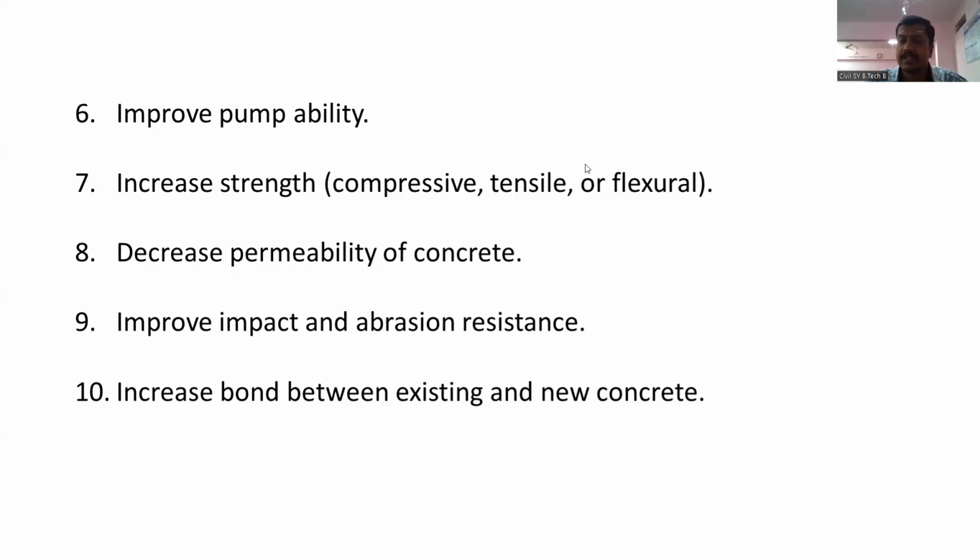And for the flexural test, we are going to cast the beam and apply the load. Maybe the beam is resting on two simple roller supports, and you are going to apply the load at the center. Okay, it's a 2-point loading method or a single-point loading method. If you apply the load on a simply supported beam and the load is acting exactly at the center, then it is 1-point loading. So there is a 2-point loading system and a 1-point loading system.